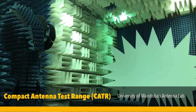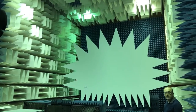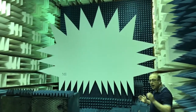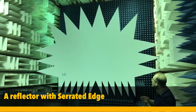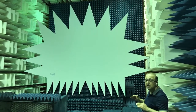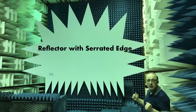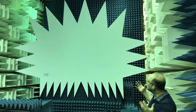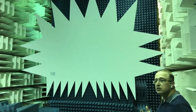Okay, we are in the compact antenna test range. What you see right now is the reflector of the antenna measurement system. At the edge, we have a configuration that we call a serrated reflector antenna. Essentially, if we don't have those serrations at the edge, we're going to have lots of diffraction, so this is to alleviate the edge diffraction. So this is our reflector antenna, and if we come closer and closer, we would be able to see the feed of the system that is illuminating this reflector antenna.